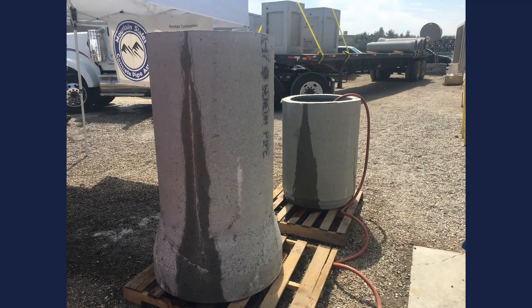The pipe that's closest to us that had been filled with water for 3 weeks and had already started healing, right? We were filling it up multiple times a day to make sure that we kept the water to the top so that it would heal all the way through the pipe. The pipe that had been healing for 3 weeks was leaking water at a rate of approximately 1 inch for every 2 hours. Okay. So it was still leaking. So it hadn't fully healed after 3 weeks, but it was leaking pretty slowly, 1 inch every 2 hours.